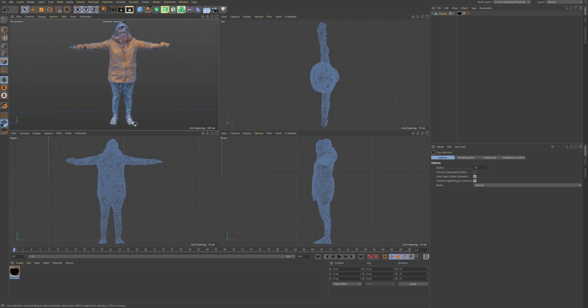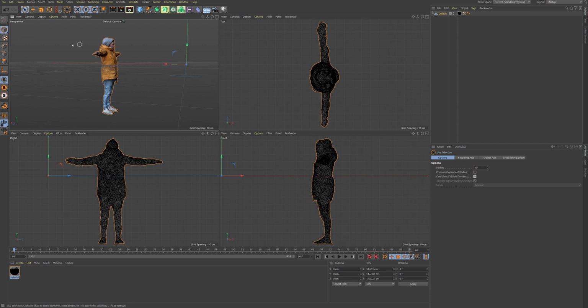Okay, now I'm done with deleting all of the unnecessary polygons. And next, I want to move this object to the world's origin. So as you can see, our 3D model is a little bit off. And to move the model to the origin, I change to the model mode. And when I press this axis, I can only move the axis, but our model will remain on the same spot. And now our front and right view and top view helps a lot by getting the correct position.